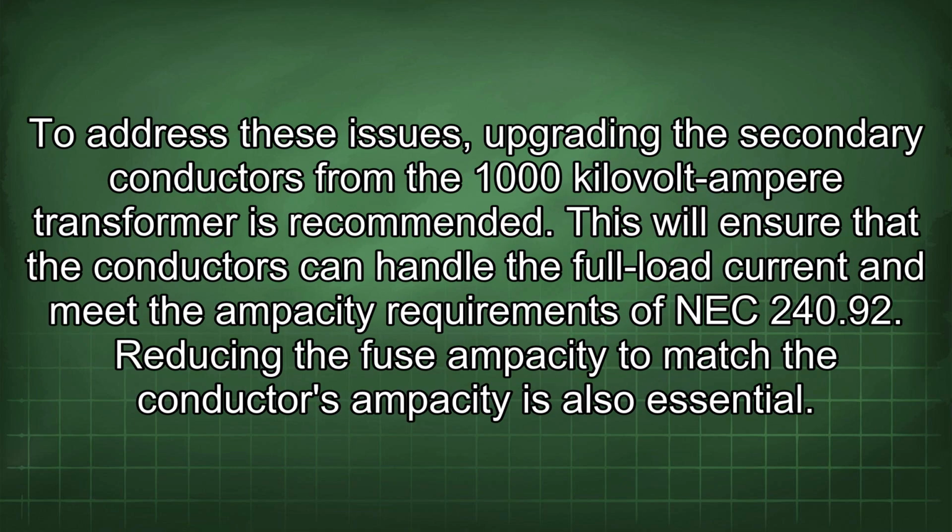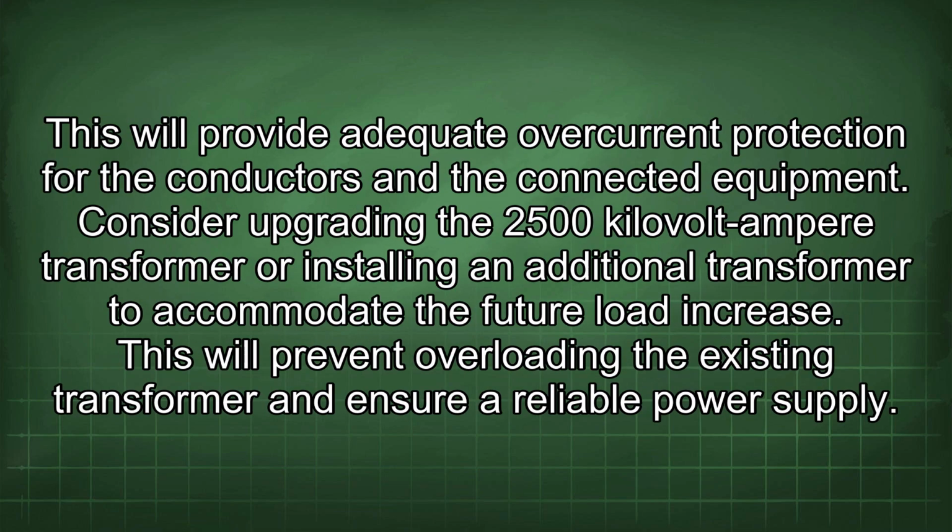To address these issues, upgrading the secondary conductors from the 1000 kVA transformer is recommended. This will ensure that the conductors can handle the full load current and meet the ampacity requirements of NEC 240.92. Reducing the fuse ampacity to match the conductor's ampacity is also essential. This will provide adequate overcurrent protection for the conductors and the connected equipment.